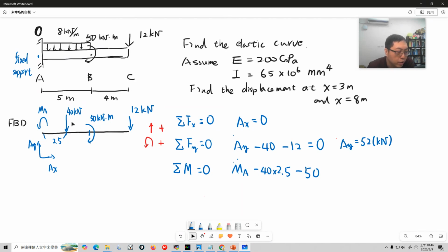This force points down, and the reference point is here, so it will create a clockwise moment. Clockwise, so it's negative 12, times what's the moment arm or lever arm? The moment arm is 9. Be careful of this, 0.9. And then equal to 0.